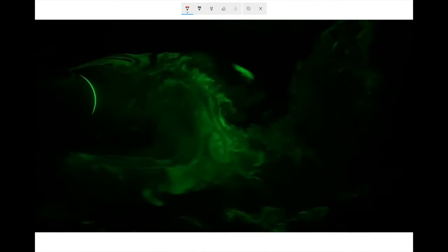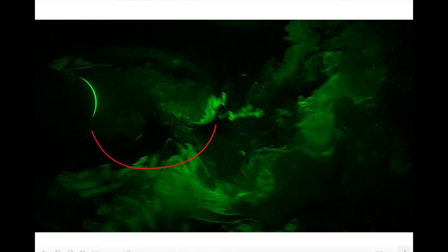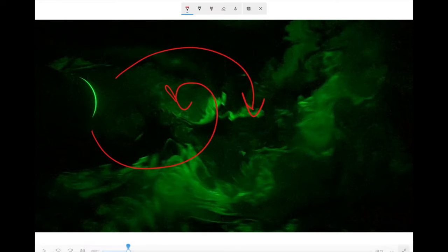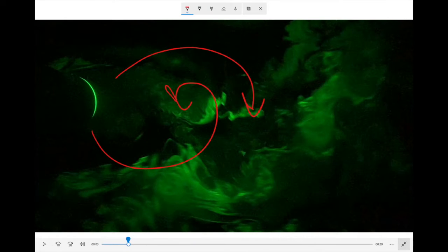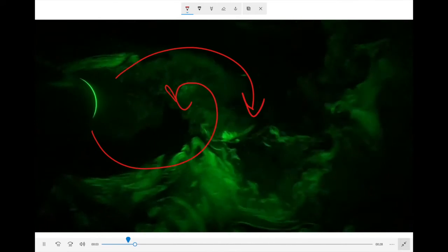This video describes the airflow that is seen behind the cylinder at a wind tunnel speed of 2.7 meters per second. In this video, you can see the wake and recirculation zone that occurs behind the cylinder. Additionally, it can be seen that vortices form behind the cylinder and are oscillating. This is also called vortex shedding.